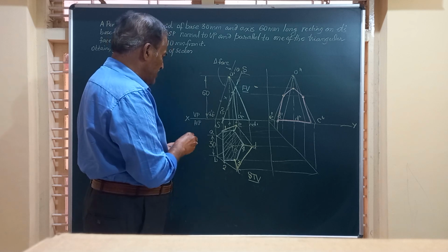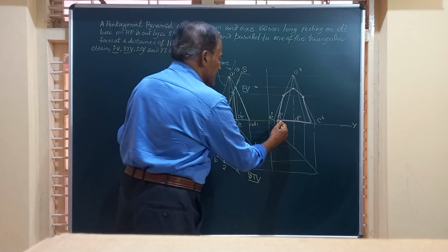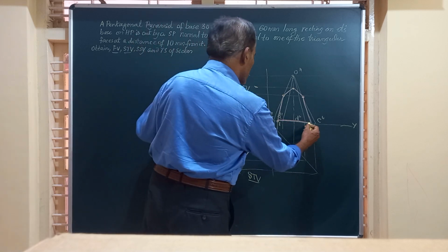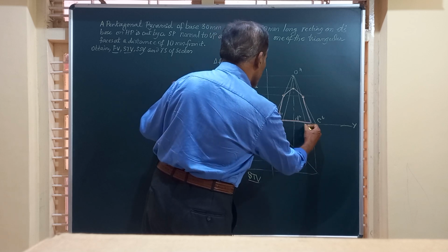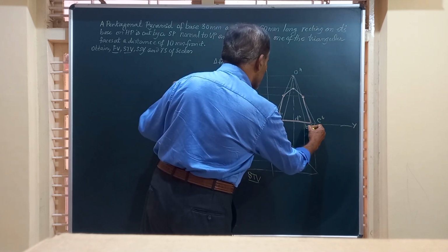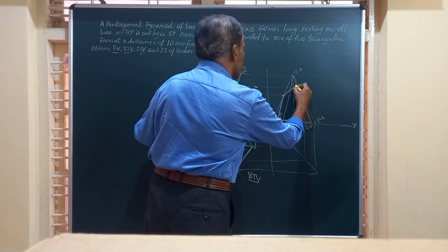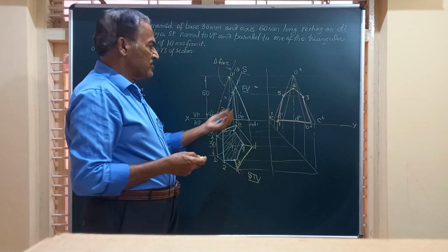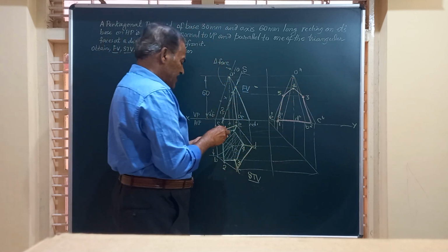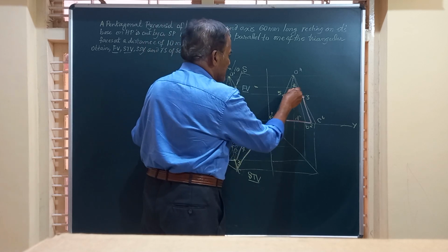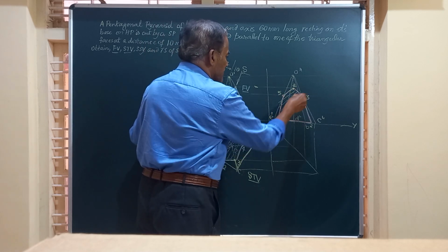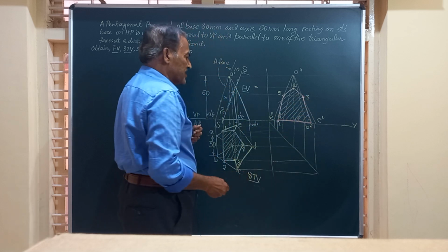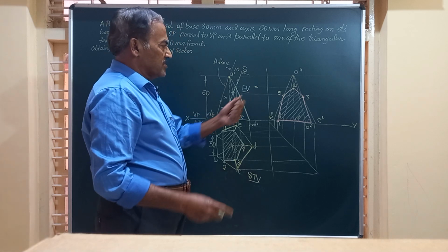Let us mark them here. So 1 is on AE. This point is 1. Then 2 is on BC. Where is point B and C? A, this is B. BC. This is point 2. Point 3, point 4, and point 5. We have got all the 5 points. And the points you have joined here have to be hatched. Have to section it by lines inclined at 45 degrees to the horizontal like this with equal spacing of approximately some 2 millimeters.